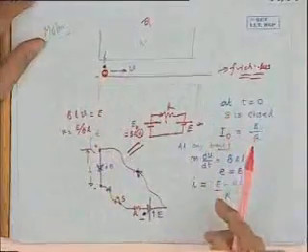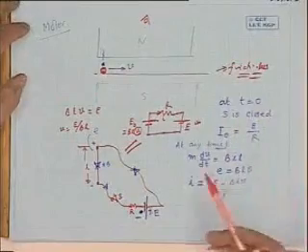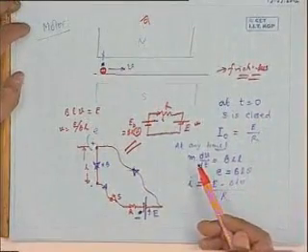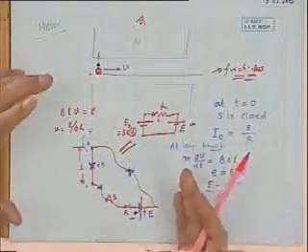Similarly, final velocity you can calculate. Current is known, therefore E minus this current into R will give you the voltage developed by the machine, which is BLV. I can calculate final velocity. Are you getting? Therefore, this is a motor. Once again, you see, when you are trying to act this as a motor, generating action you cannot avoid. It will automatically be present.